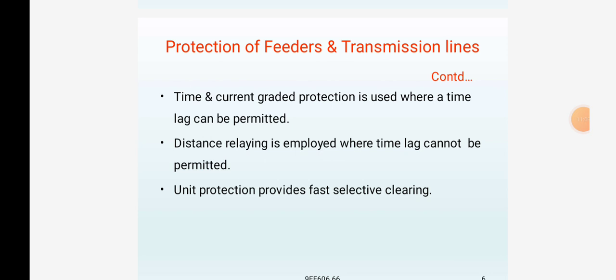The secondary of the CT is connected to a sensitive framework leakage relay. In the event of earth fault currents flowing in the switchgear framework, this relay will operate.